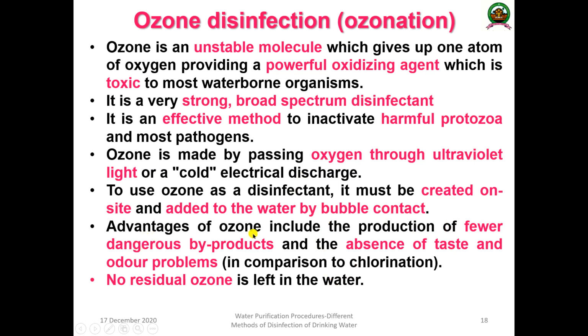Then the advantages of ozone include the production of fewer dangerous byproducts and the absence of taste and odor problems that are very common in chlorination. Not only that, no residual ozone is left in the water. Although it is an advantage, this seems to be a disadvantage also.